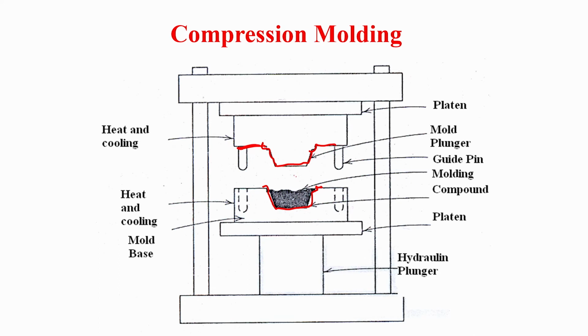So, you have a male and a female part in the mold design. Then you can fill the cavity with the polymer powders, and the top punch can be lowered and pressed. There is also a pencil heater attached to this platen. Through this pencil heater you can locally heat the lower part of the mold, and as a result, by the application of heat and pressure, these polymers can be shaped into a particular product.